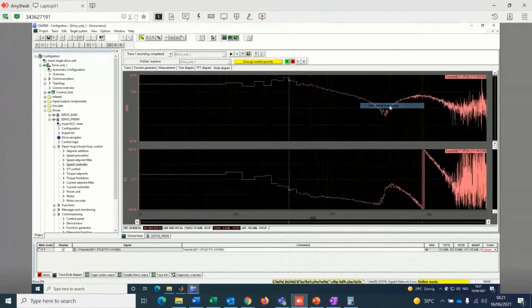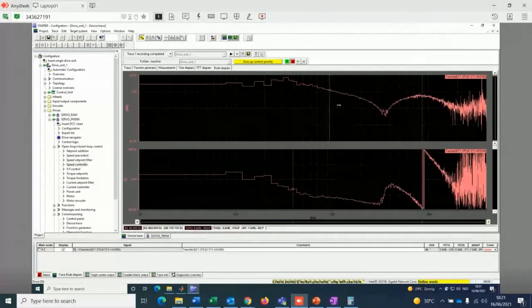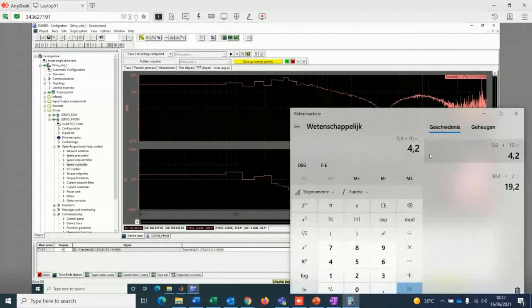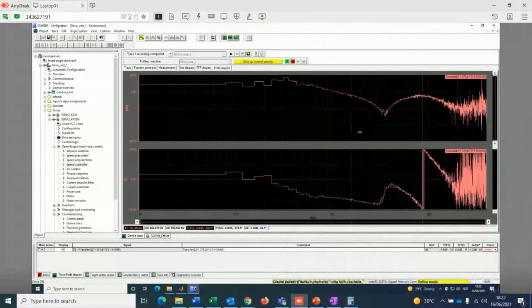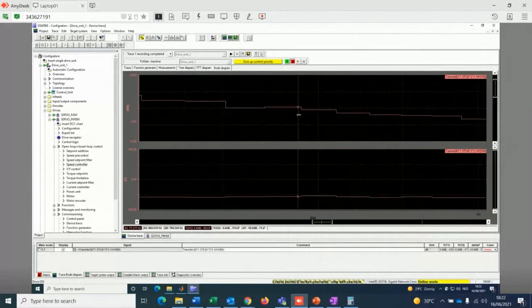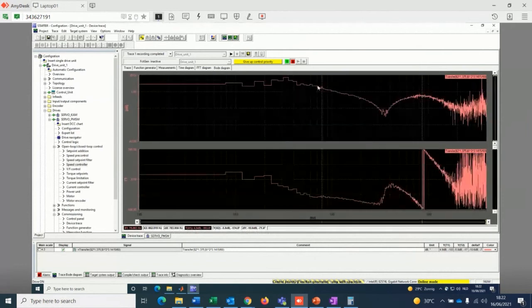Now we will go here in the magnitude curve with the other cursor, and we will find this magnitude, 4.2. So here we will move our cursor until it's somewhere here. We see that due to the resolution, we cannot achieve the exact value. So we have either 3.9 or 4.9. So we will go to the higher value, just when we cross to the higher value. And then we will take that point for the design.